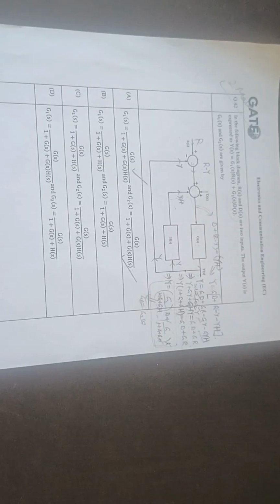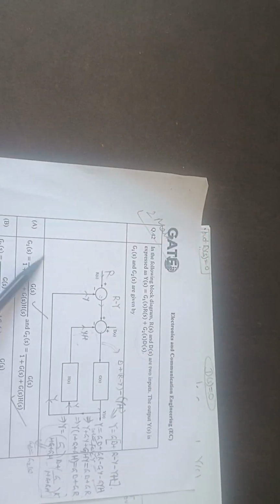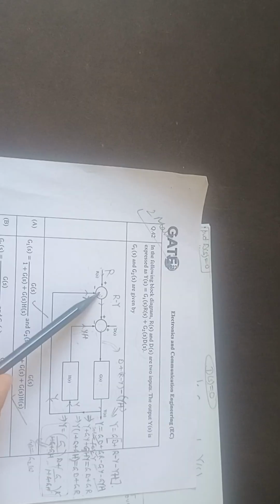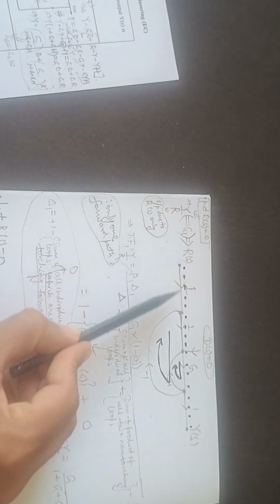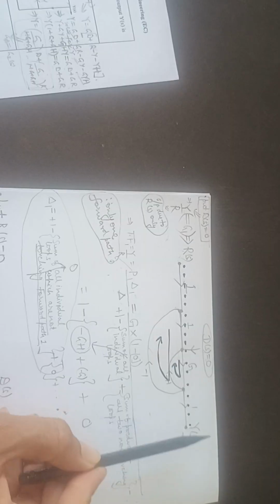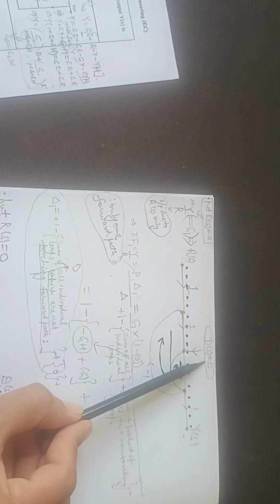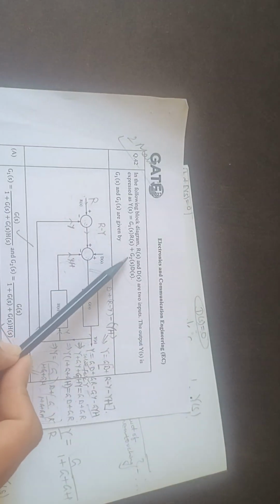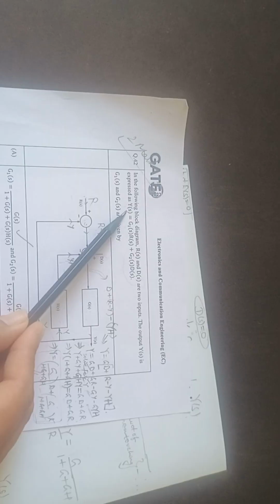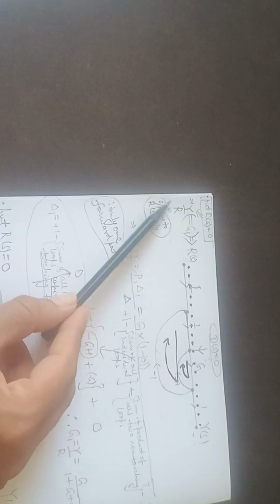Or if you want to use the signal flow graph approach, then you can convert it into signal flow graph as this input node, then second, third, and then this fourth, and then this output node. 5 nodes we will take. So 1 2 3 4 5, and in case 1 we will find Y(s) upon R(s) when D(s) is 0, because when I put D(s) equal to 0, then Y(s) upon R(s) is equal to G1(s). So G1(s) will be equal to Y by R(s).